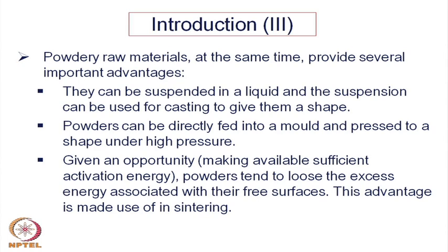So the powders, when heated to high temperature so that certain activation energy is provided to the system, tend to lose their excess energy, particularly the surface energy, because of the high surface area. This is the process which is taken advantage of in sintering.